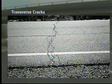First, we want to explore the distress conditions, causes, and cures for flexible asphalt pavements. Let's begin with the general issue of cracking. Transverse cracks appear at approximately right angles to the center line. They're caused by temperature changes and shrinkage of the asphalt with aging. Cures include crack sealing, chip seals, and thin overlays.